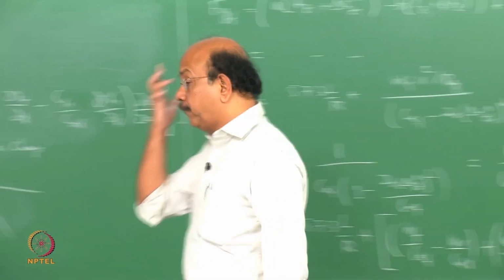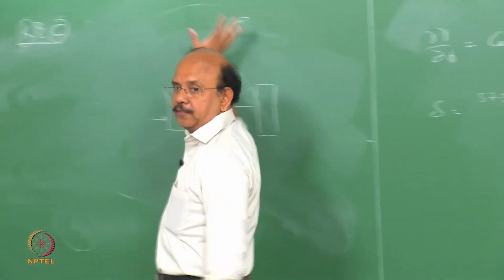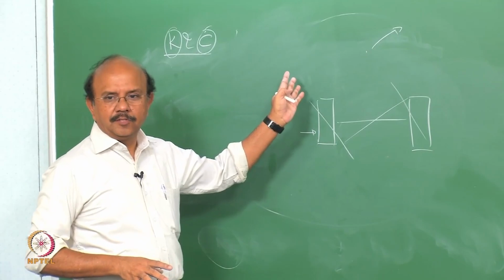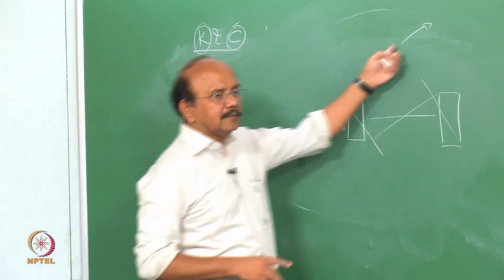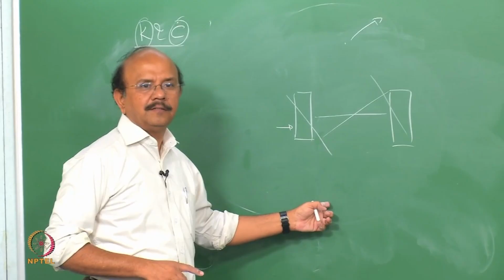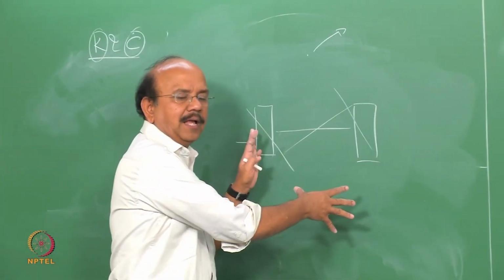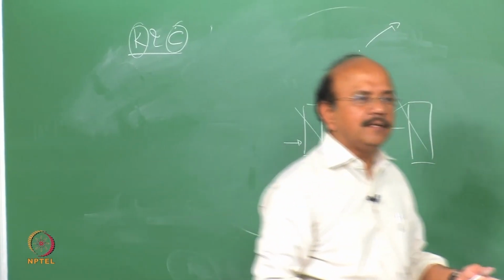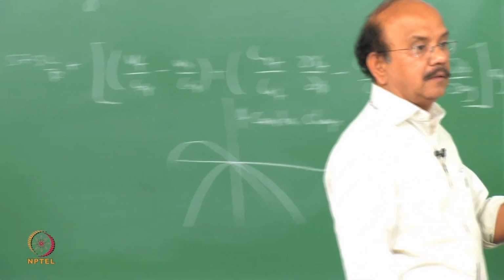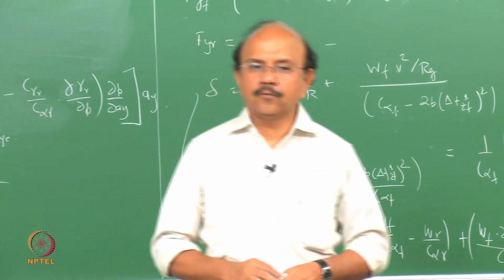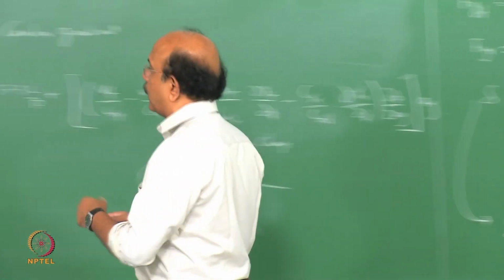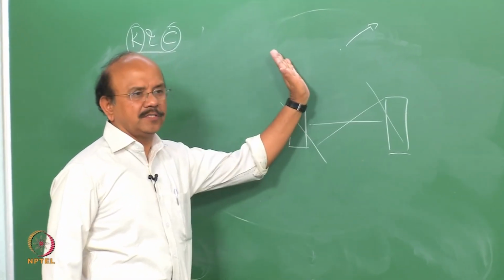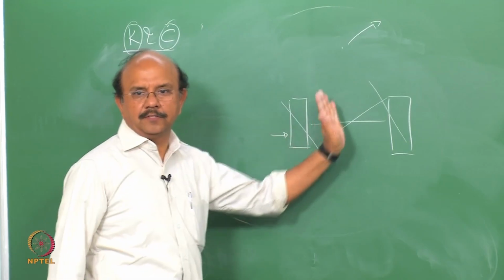Okay? So suppose this is the rear, and if this is what you are going to do, fine, this would cause an oversteer. On the other hand, if this happens to be behind, and you are taking a turn and the wheels go towards the left when you are taking a turn to the right, then that would cause understeer. Sorry, first one is oversteer and the second one is understeer. First one, because you want the rear to go like this for making your turn easy, so when it turns to this, I think I slipped, this is an oversteer.